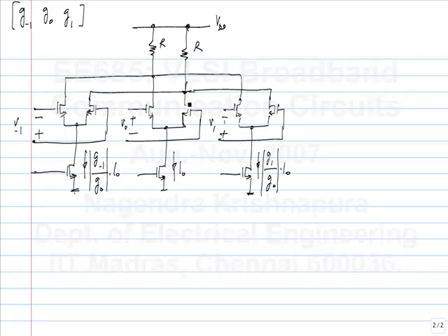What is the primary difference between Nmos and Pmos? Mobility is higher. So what is the consequence of that? So GMs will be greater for same currents. Okay. So does it make any difference to this circuit? Yeah, we can have smaller transistors for Nmos. Let's say you want the differential pairs to switch at a certain voltage, and you want to switch a certain amount of current. Then the size of Nmos transistors will be smaller than that of Pmos transistors.